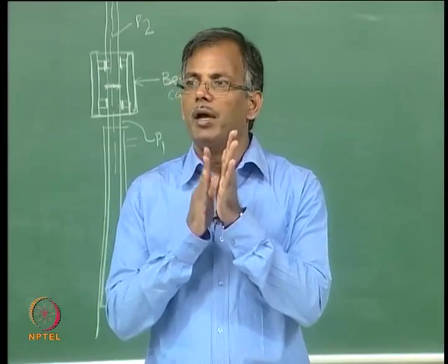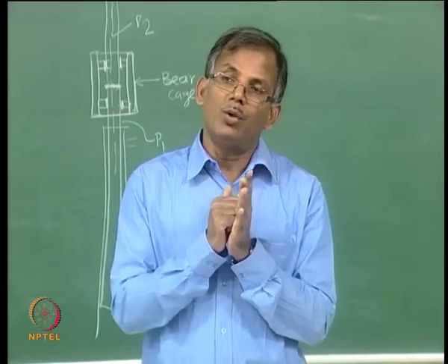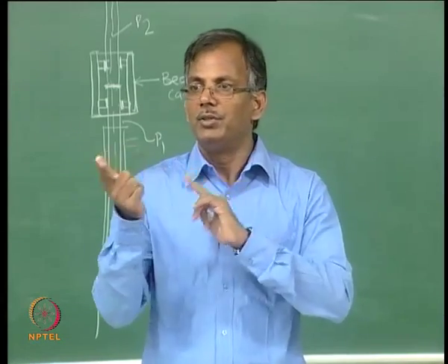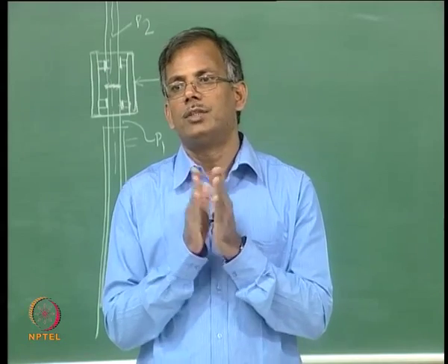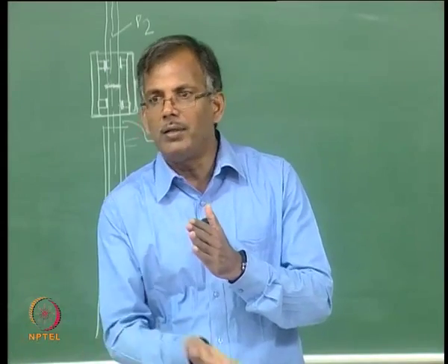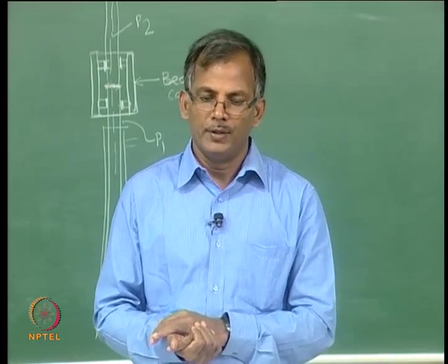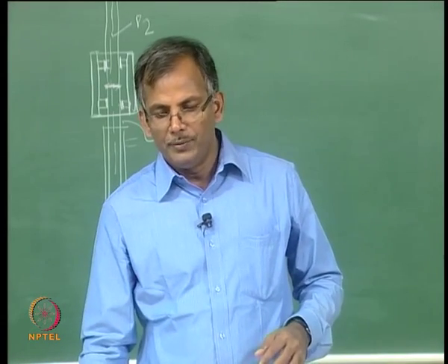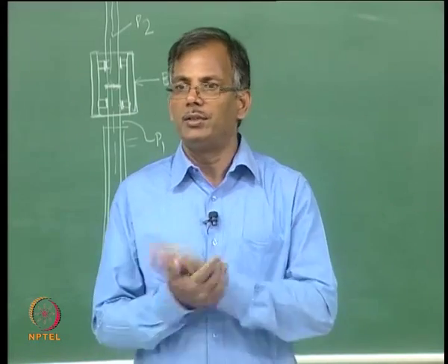There will be plastic deformation of the soil while you strike. If you still want to work within the elastic limit, that means the pile cannot be driven. You have to break the bond between the soil and the pile, and at the bottom the soil has to undergo plastic deformation, and only then will the pile go down. If it is not feasible, that means the pile could not be driven, either because the hammer is small or the soil is stronger.